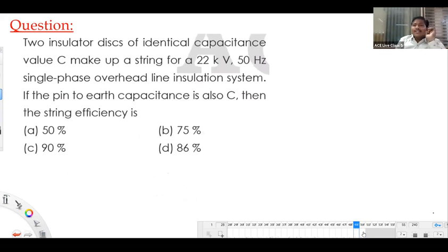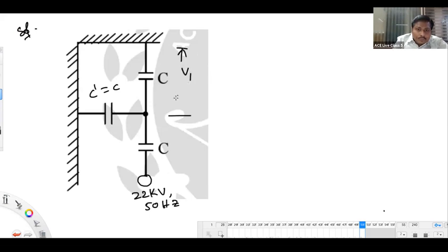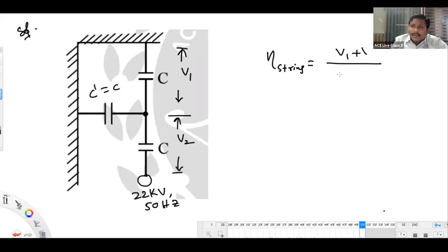Kindly listen to me. He is asking about string efficiency calculation. You take the topmost disc voltage V1, the next disc V2. The string efficiency formula for a 2 disc string is (V1 plus V2) by (number of discs, which is 2, into the highest voltage across any disc, which is V2).